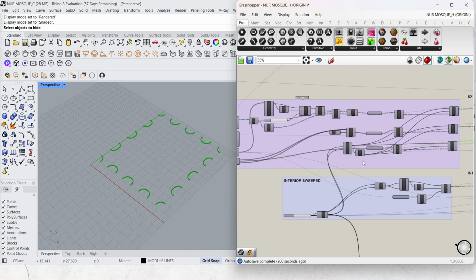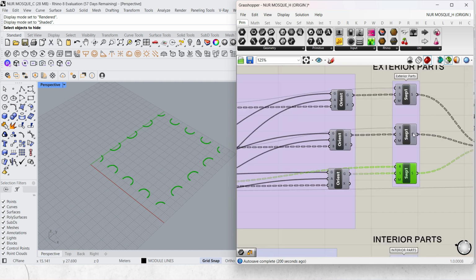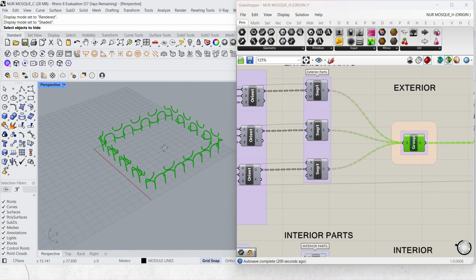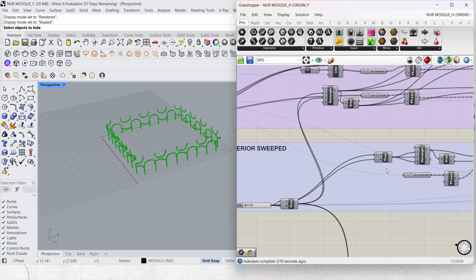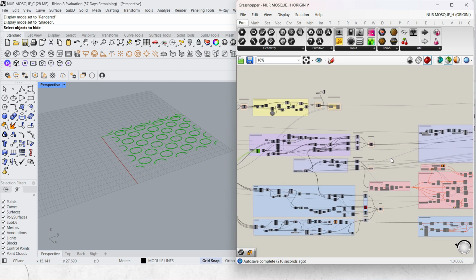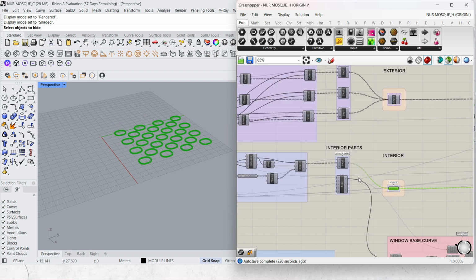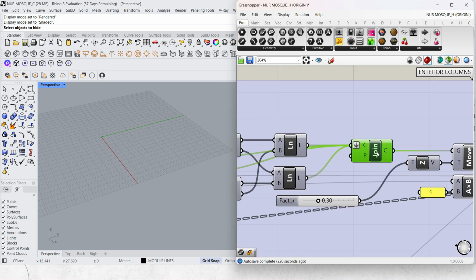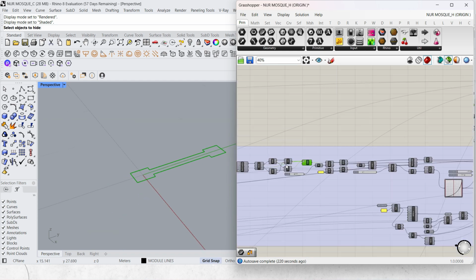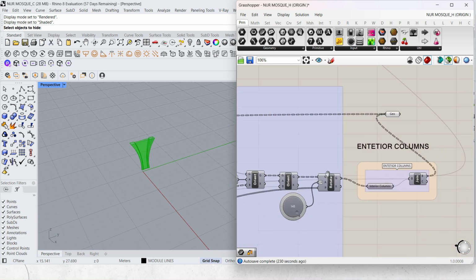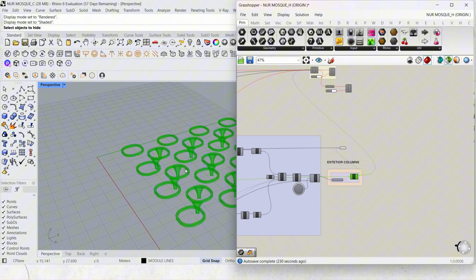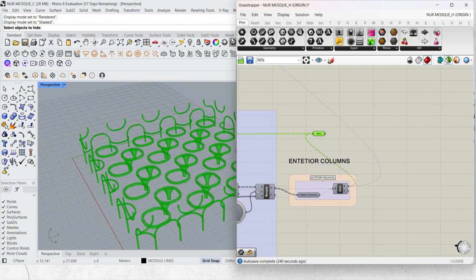Using the same open curve endpoints, we can make the columns, which by that will be done by the exterior part. Moving next to the interior part, which is by using the same arrayed curve, we sweep it, and then doing the column by taking this shape and then moving it and scaling it by the use of graph mapper, lofting it to create the column, and then orient it to different circles to create the exterior and interior part.